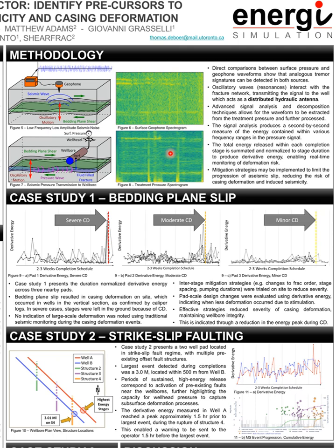And essentially what this allows us to do is treat our surface pressure gauge like a distributed hydraulic antenna. This allows us to capture seismic waves that are transmitted through that fluid pressure collected at the wellhead, and these can be transmitted and processed in real time using an advanced signal analysis and decomposition technique.